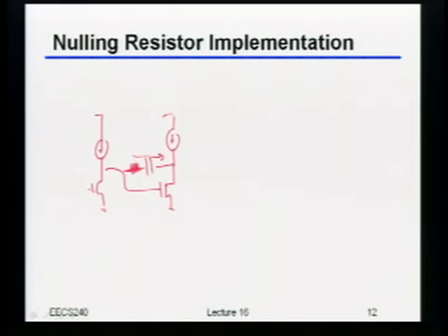Then we talked a little bit about how you'd actually implement that resistor, given that you really want that RZ to somehow be related to the 1/GM of that second stage. So there were some issues there. We said there are some clever techniques you could use. But what I want to briefly cover now is what if we could actually do this Miller compensation, in other words, add in this compensation cap right here, but do it in a way that didn't have a feed-forward zero, so we don't have to worry about its impact on our overall stability.